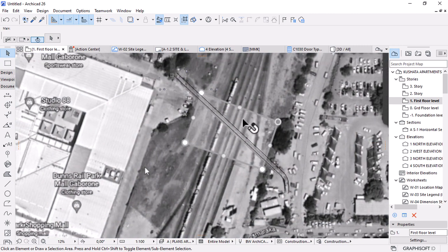So what you need to do is to sketch our layout before we can play around with some concepts. So I'm going to use a spline tool. It's important to understand how these types of lines work. We have a line tool, which is just a single line, and then we have a polyline tool and a spline tool. They work differently, and you cannot use a spline tool anywhere you want. It has a specific role it will play in your design. Same applies to the polyline tool. So each has its own role.